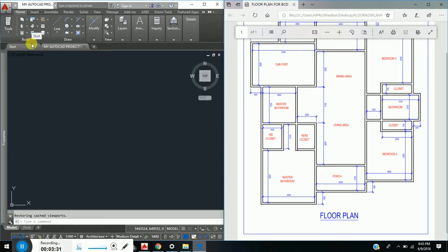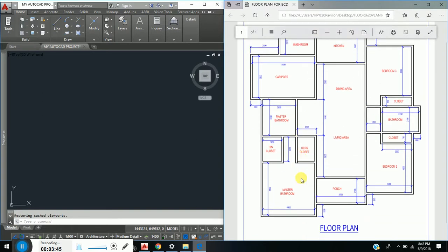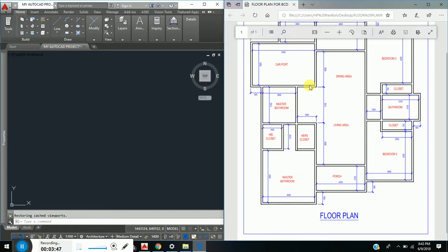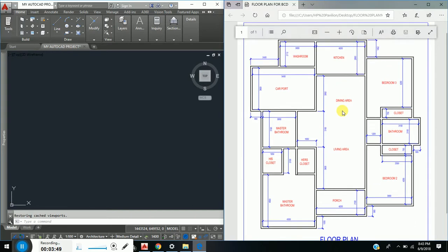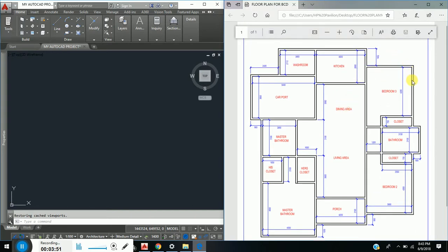Now, the first thing we have to establish are some basic dimensions in terms of what size these walls would be. Most of this building will be accommodating a pitched roof, and basic heights for walls accommodating a pitched roof would be approximately 11 feet 6 inches.